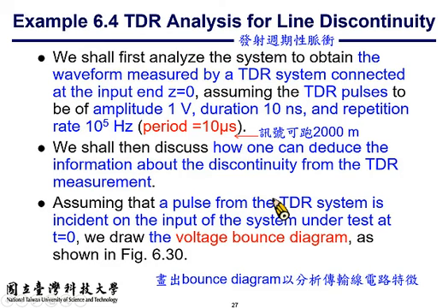And here is some additional information that we discussed on Tuesday. We say the repetition frequency is 10 to the fifth, which provides a sufficiently long period of 10 microseconds, so that all the energy injected by the pulse generator will be dissipated on the transmission line, because the transmission line comprises not only the shunt resistor but also a matching load at the left end.